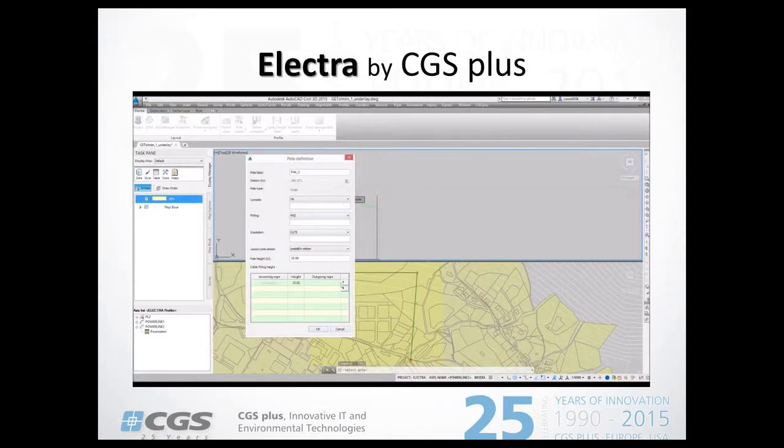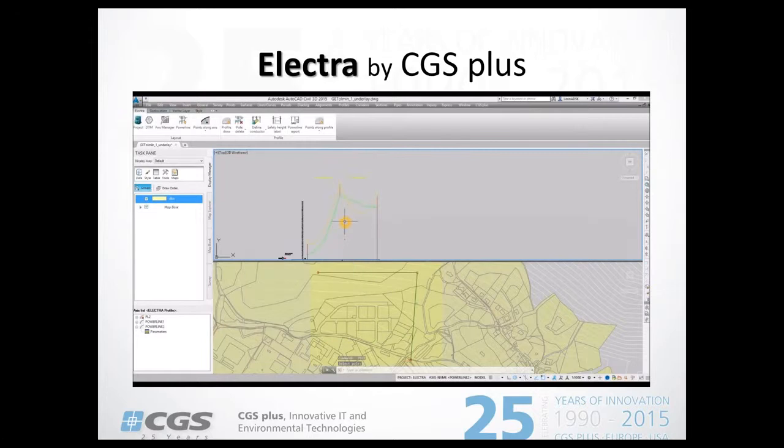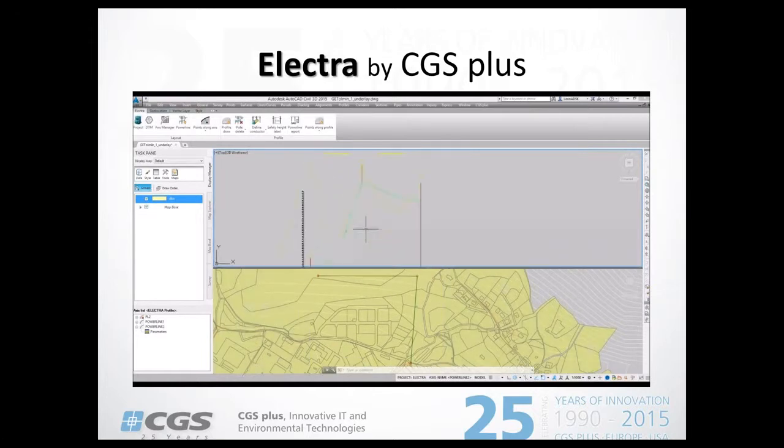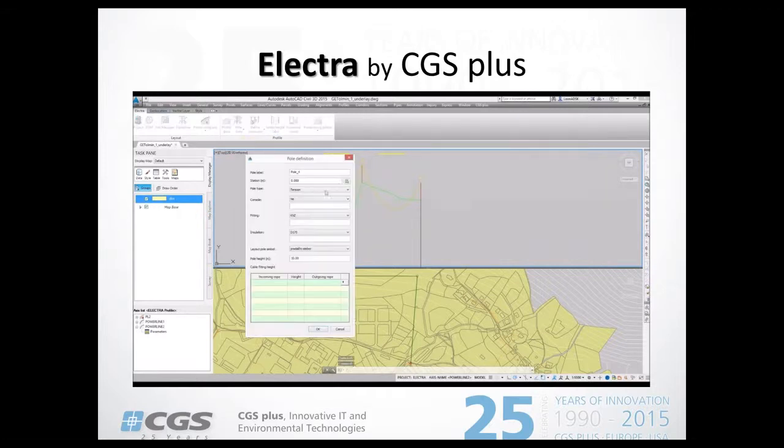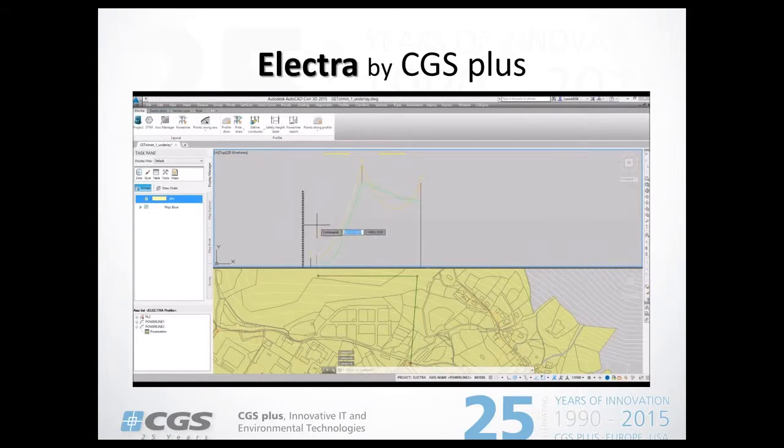additional poles. Okay, so in the next section, here's another conductor, and as seen here, we just need to add some poles here. So we will put some support poles, and as seen, as we move in the profile, the preview of the catenary sag is already seen.